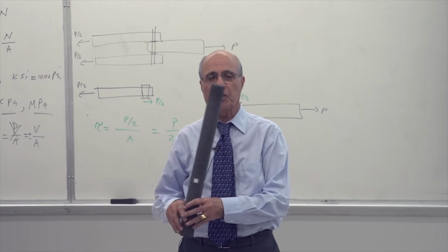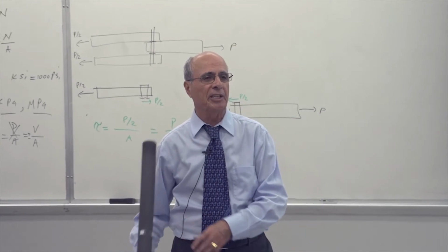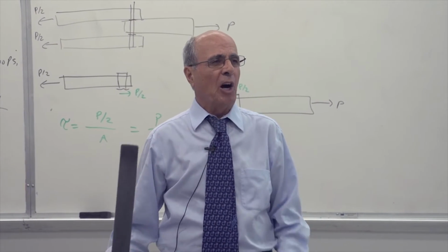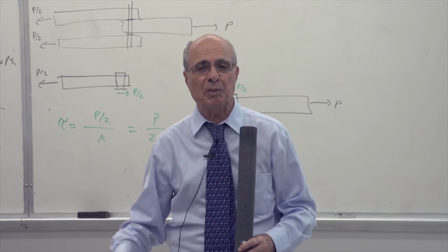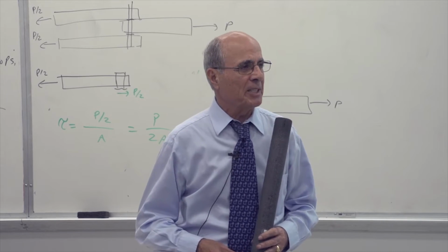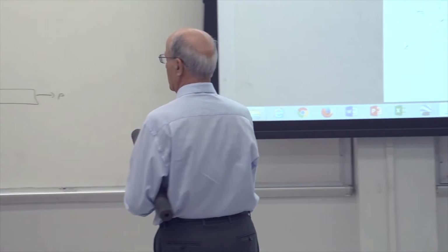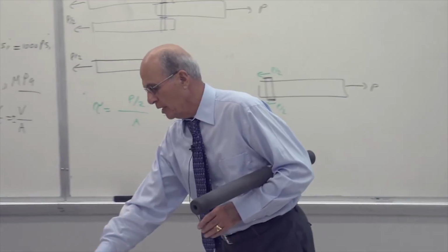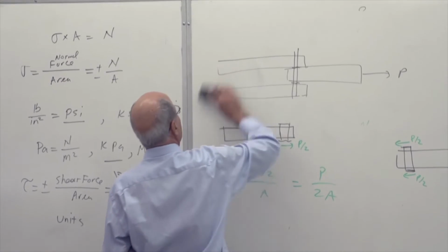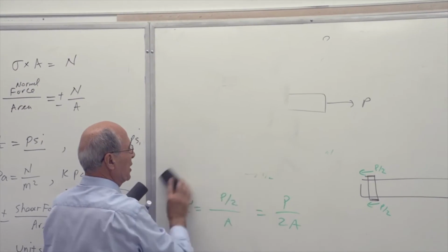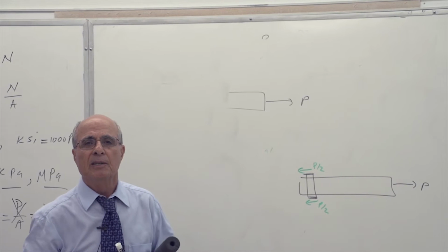This is normal stress or shear stress on the wood, what I'm creating? Normal stress. However, this is a little bit different from this stress because this is the stress between two different materials. We call it bearing stress. So please write it down. Although it's normal stress, your guess was absolutely correct. So one of the variations of that, I'm going to put here in front, is the bearing stress when two different materials are touching against each other.